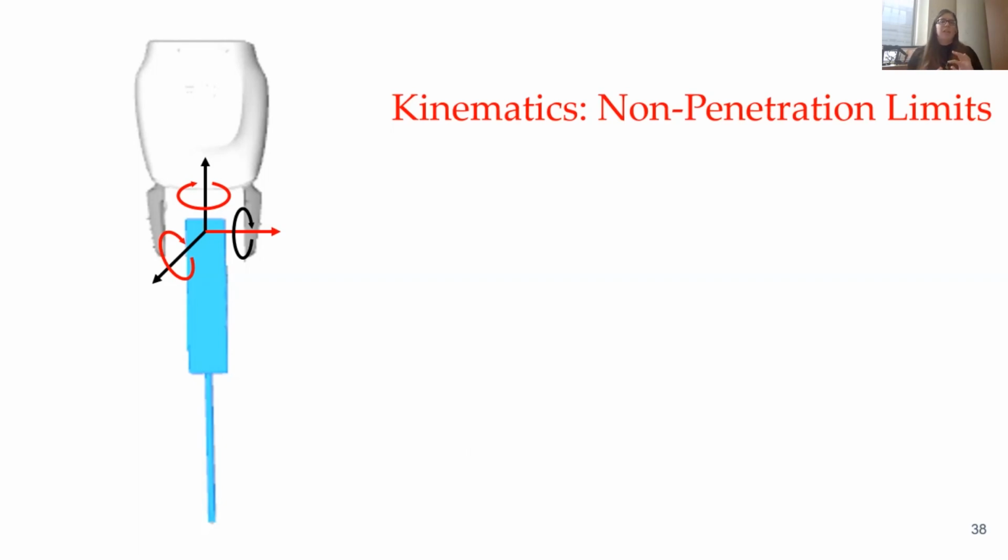And so we're going to assume that in these 3 dimensions, because our hand is rigid, we can resist an infinite amount of force and torque. This assumption has held for me all but once, when our robot fingers cracked in 2 and we had to reprint them. But otherwise, we're going to assume that our joints are rigid and we can resist infinite force in these 3 dimensions. What about the other 3 dimensions? In the other 3 dimensions, it actually is valid that our object can move within our grasp.